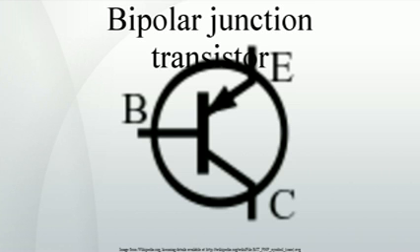If the emitter-base junction is reverse biased into avalanche or Zener mode and current flows for a short period of time, the current gain of the BJT will be permanently degraded.